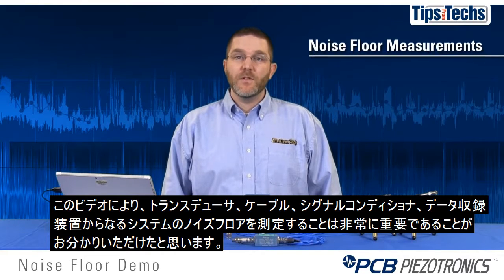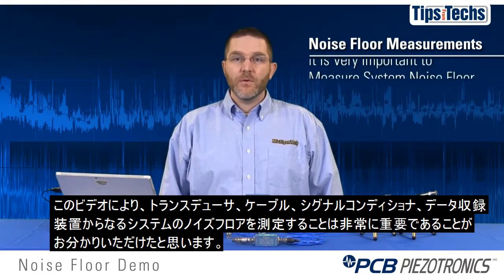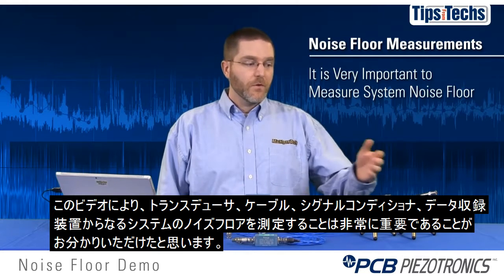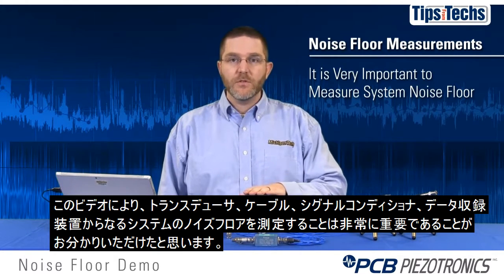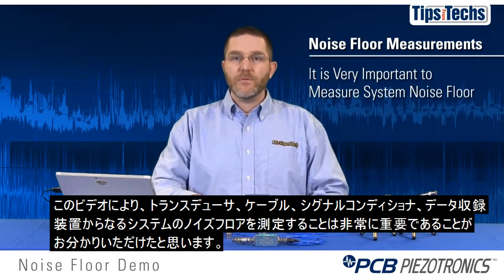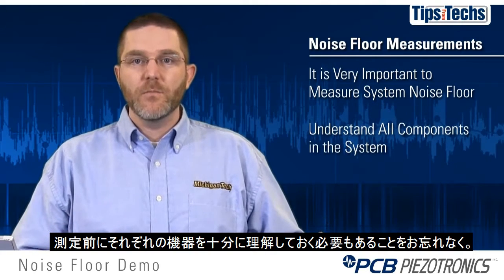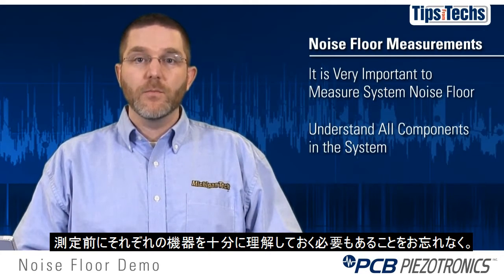So the takeaway from this video is that it's very important to measure your system noise floor from your transducer through your cables to your signal conditioner and into your data acquisition system, and understand each of the components before you go and take a real measurement.